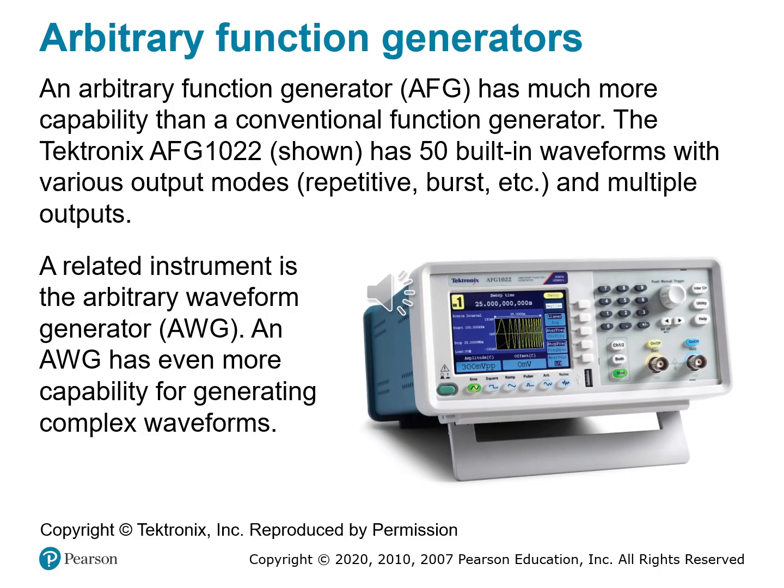And why does this matter? In modern electronics, you're not always dealing with clean sine waves. You need to test noisy data streams, mixed signal systems, power ripple under switching loads, communication bursts and packets. And that's where the arbitrary function generator shines. That means you define the waveform, not just choose from a list. So from classroom labs to advanced research, AFGs and AWGs let you simulate the real world signals that circuits must handle. Some of you actually have AFGs in your lab. Some of you have the traditional function generators.